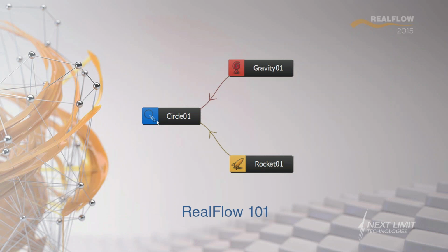RealFlow is about dealing with fluids, with particles, with emitters on one hand. On the other hand, we have to deal with forces and geometry. RealFlow as a standalone application will talk to your 3D platform. Basically, the workflow, we will see it in a minute, is about bringing geometry into RealFlow, simulating, generating the fluids, meshes, particles, whatever, applying the forces and setting up the colliding geometry that we will use in our project.